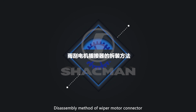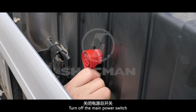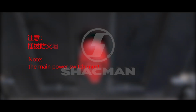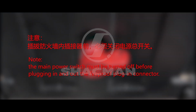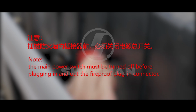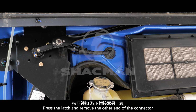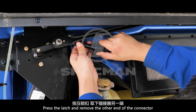Disassembly method of wiper motor connector. Turn off the main power switch. Note: the main power switch must be turned off before plugging in and out the fireproof plug-in connector. Wiper motor harness connector. Press the latch and remove the other end of the connector.